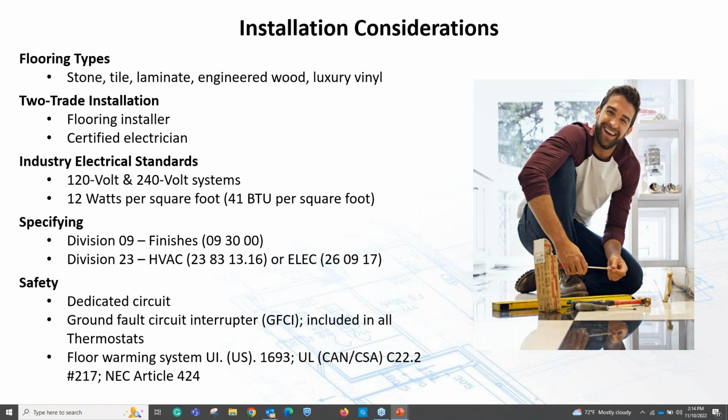Most all the systems out today are going to be a 120 or 240 volt system. The standard amount of heat that's put into the floor, by most of the manufacturers, is 12 watts, which guarantees that you can warm the tile surface. Let's say you're doing stone, 3/4 inch stone, it'll warm that stone surface, be nice and warm, and you can keep it up at a little higher rate to warm the whole room, or you can have it just take the chill off in the morning. That's kind of up to the customer what they want to do.